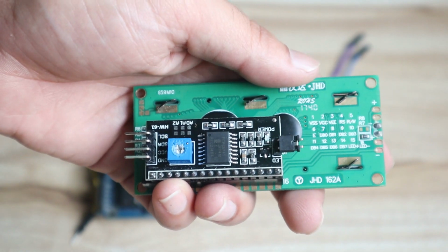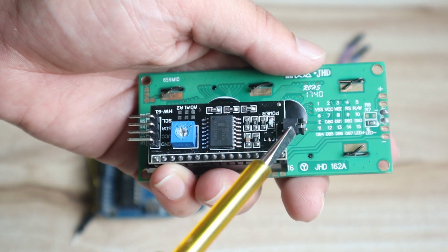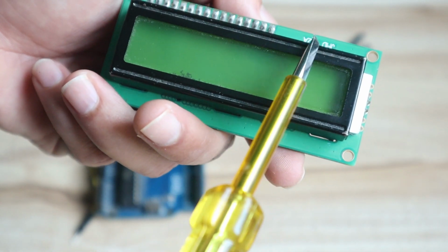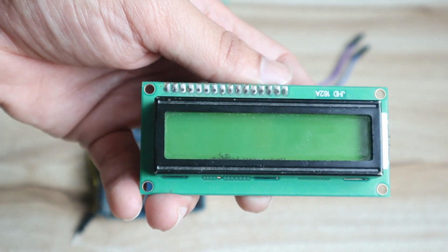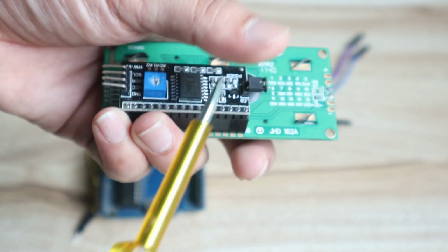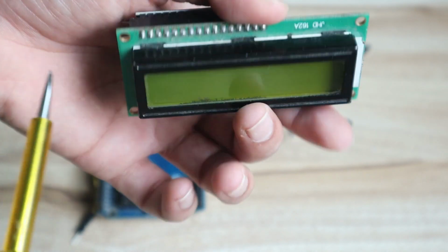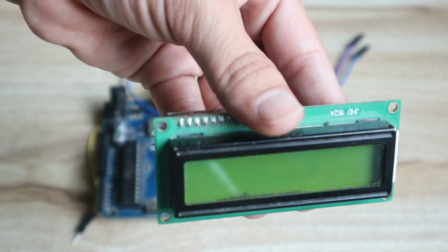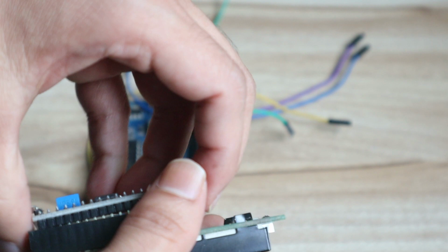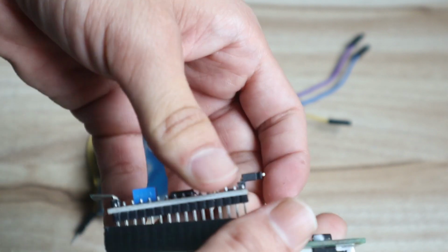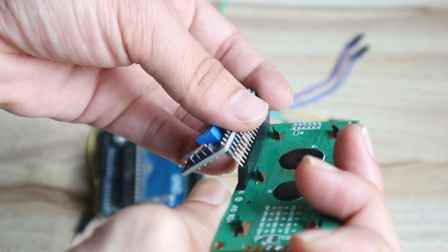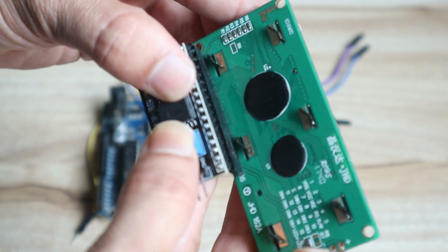Now please pay attention here. This point of the i2c display should be at this side of the LCD only. You can see this is my LCD. If I take this LCD and move this, then this point should be at that side, and this point should be at this side. You can see this side only. So your display should look like this. Because I made one mistake, I connected this i2c module like this, sorry. I can show you what mistake I made, so that you will not repeat this mistake in future.